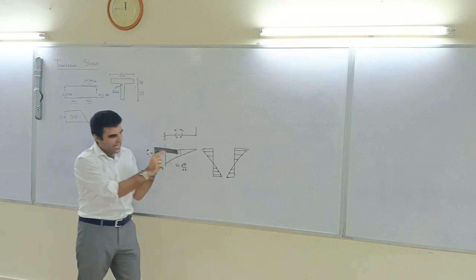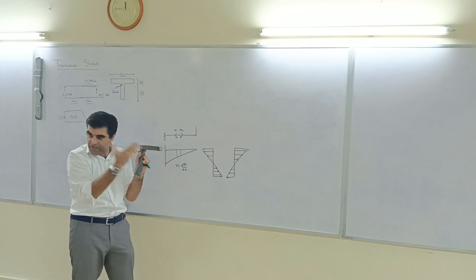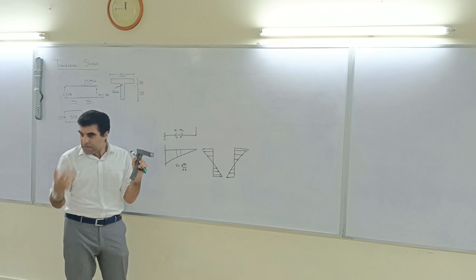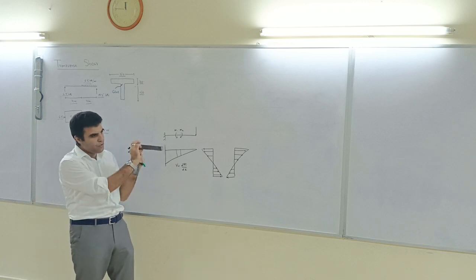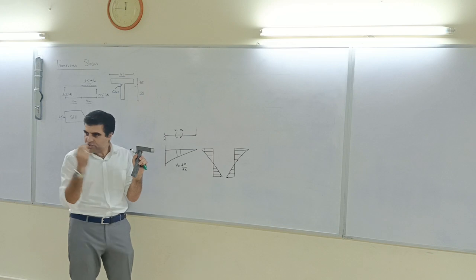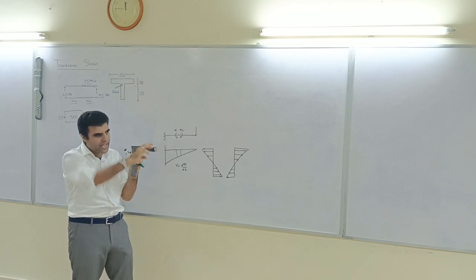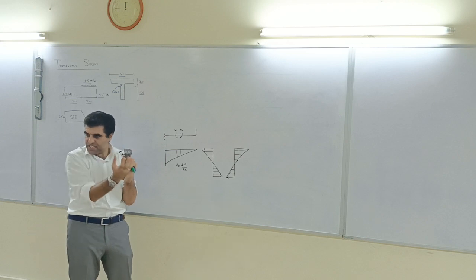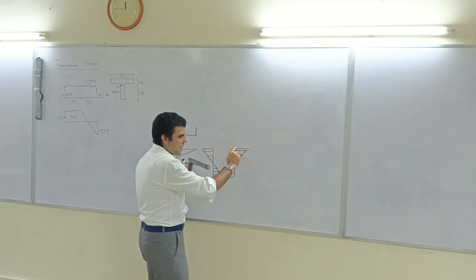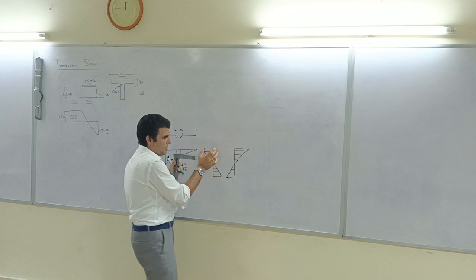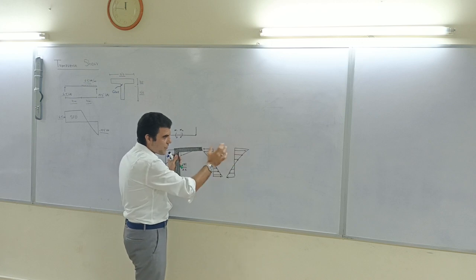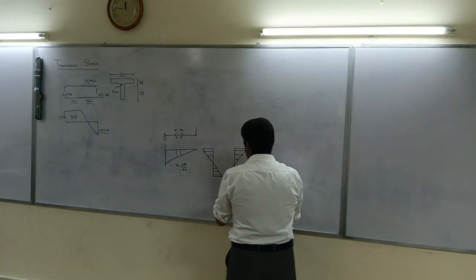In the case of a beam, a structure is a 3D element. A beam is the simplest structural component. So if you consider a beam, you can divide it into lots of small boxes, which I have shown over here. These are all made up of these boxes. At a particular box you will have a force which goes like this, and at an adjacent box you will have a force which runs like this, and the difference between them will give you a shear force.